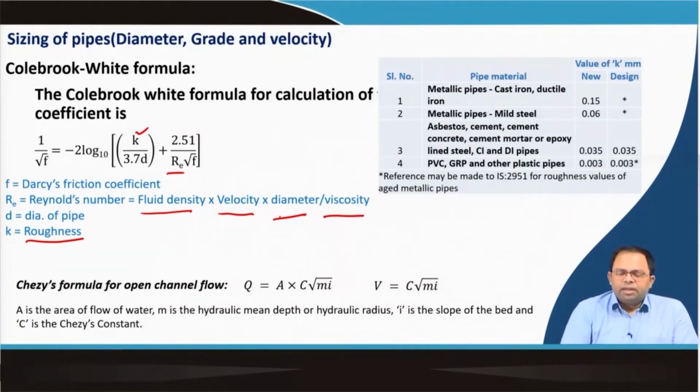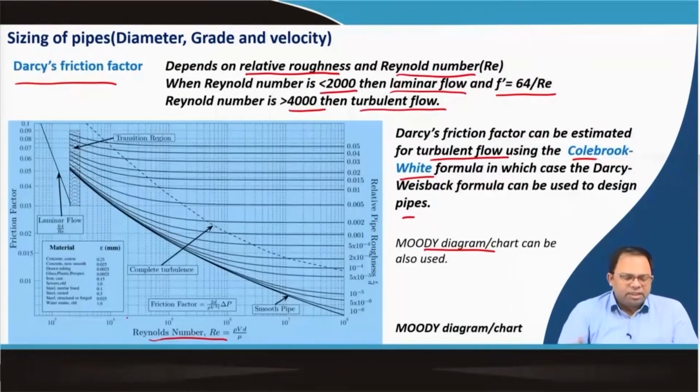So, these are the different things that play a role in determining Reynolds number and what kind of flow will happen. So, Reynolds number determines if it is a turbulent flow or a laminar flow. Like you can see that this range is the laminar flow part. This part is a transition zone in between, that 2000 to 4000 part, and beyond 4000 we can call it definitely a turbulent flow.